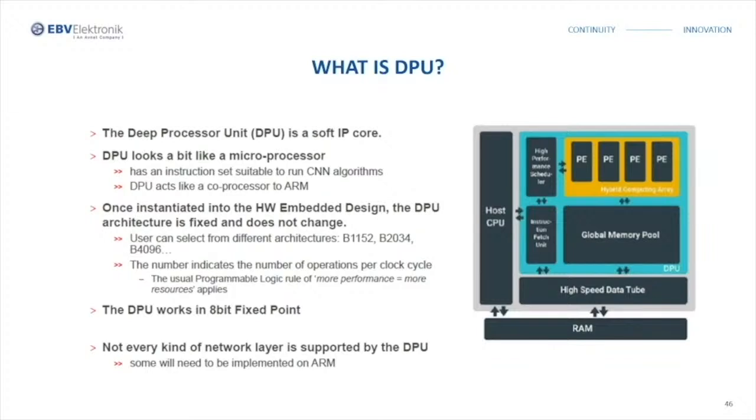The DPU IP can be integrated as a block in the programmable logic side of the selected Zynq devices, with direct connections to the processing system. To use the DPU, we should prepare the instructions and input image data in the specific memory address the DPU can access. The DPU operation also requires the application processing unit to service interrupts to coordinate data transfer.